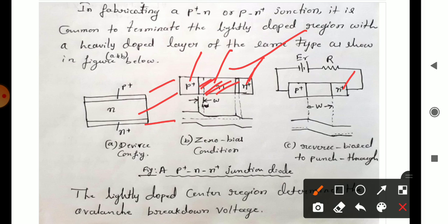So like you can see over here, this is a P plus region and N plus region, this is a width that is covered by the heavily doped P region. So in order to get an ohmic contact, I should have an N region, but this P plus region will penetrate deeply towards the N region. So for that reason, there won't be any ohmic contact.